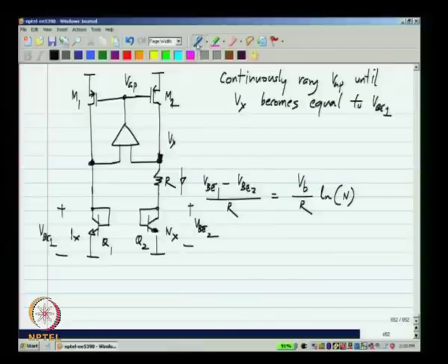In that case, what you do is, you have to pull a current using this NMOS transistor, and if you make this gate voltage high, it will pull the current. So, what can be done is a circuit of this sort. Okay. Now, this PMOS transistor will pull the gate of the NMOS transistor high if its gate is at 0.